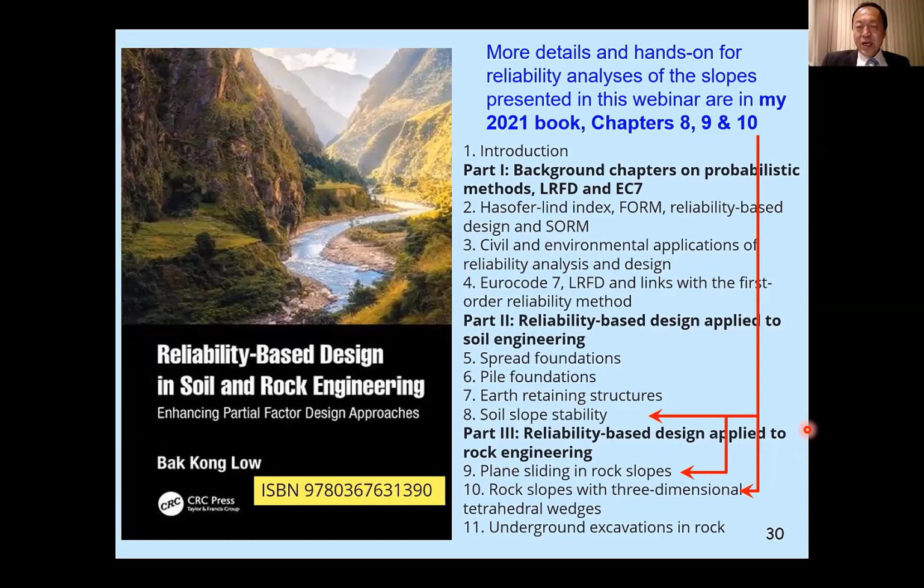If by stochastic simulation you mean the reliability approach, reliability analysis and reliability-based design, as opposed to Monte Carlo simulation, yes, there's a difference. In Monte Carlo simulation, you can get a probability of failure, but you may not have the insights and interesting information relating to the design point, where the expanding dispersion ellipsoid touches the limit state surface.